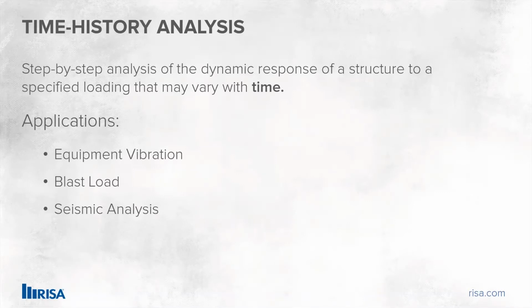So this is a more direct method compared to RSA, where you plug in the period and you get your response. Time history analysis can be used not only for seismic, but also for analyzing equipment vibration or blast load, for example.